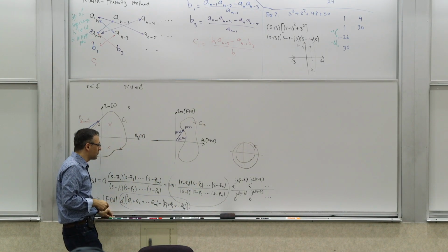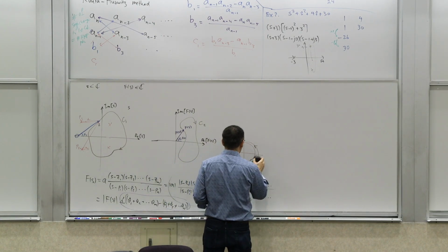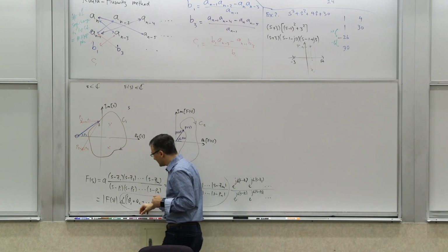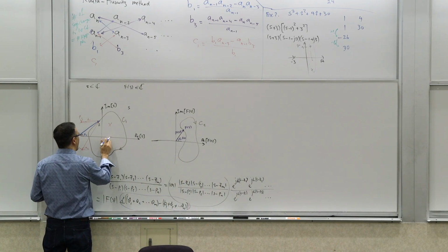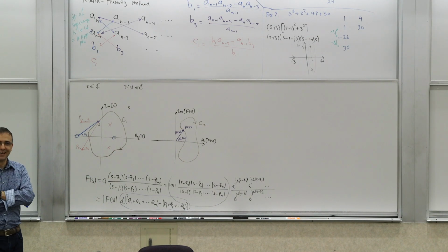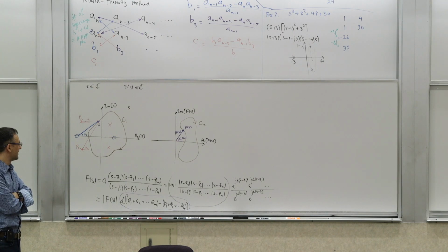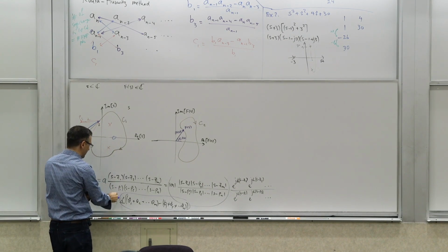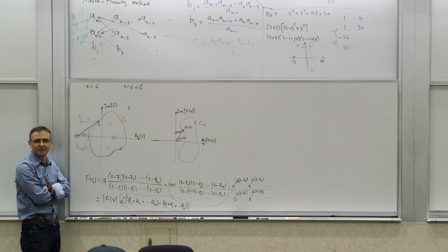So from this, what we can tell is something important and relatively straightforward. And if I had zeros in there, what would happen? So let's say now I had a zero there too, a right half plane zero. What would you end up with? How many turns? We only encircle once. Encircle once and counterclockwise, right? Because this one would produce a phase that would be counter to that.